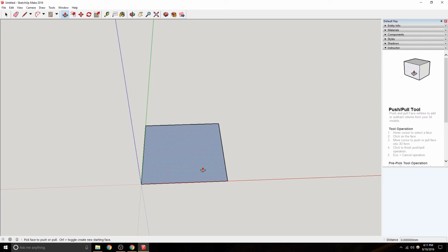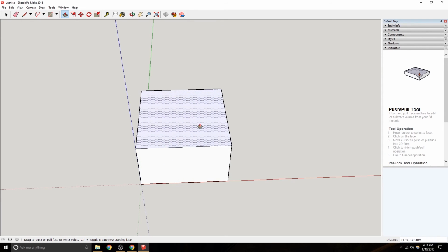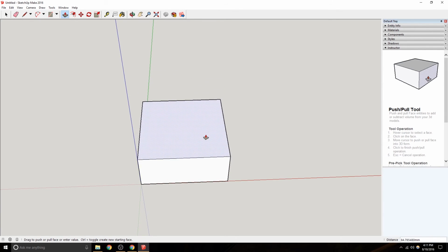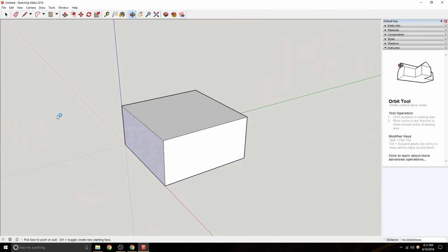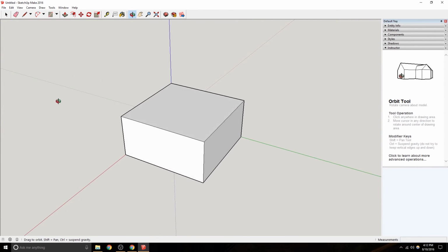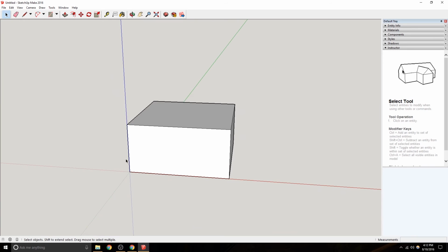I also have an extrude button. Control Z to undo. So click once and lift. And the extrude just lifts in one direction. So let's lift it 100. And so that's half the printer height, but full X and Y. Notice your axes, your blue, green, and red. Your red is your X, Y is green, blue is Z on your printer. 0, 0, 0 is right there.